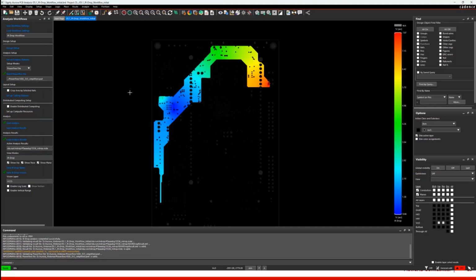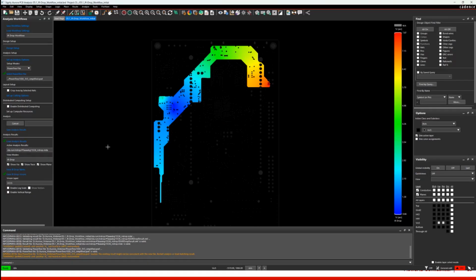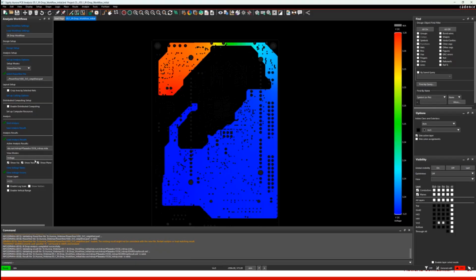As we've already learned, we have already created this power tree. We use the 3.3, and we can also run this simulation directly once we have loaded the power tree. I think this is a very, very fast way to get the results, and you see how this can be done. Here we can see now the IR drop, or even the voltage or current density.